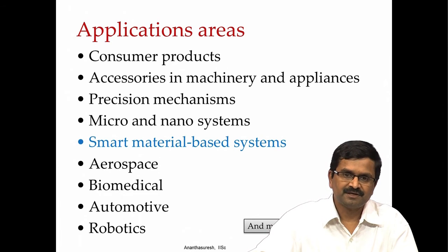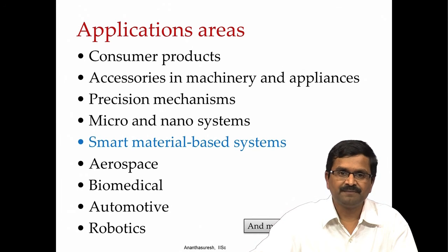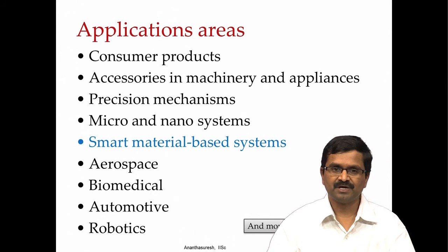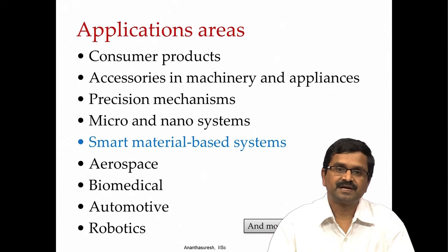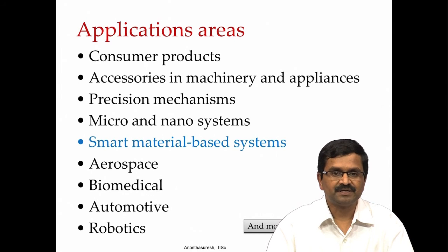Many of the smart materials are so called active materials, especially, let us say, piezoelectric ones. It can give you a lot of force when the stroke is small. In fact, most of the piezoelectric materials, when they are stacks or otherwise, compared to the force that they can deliver, the displacement is quite limited.